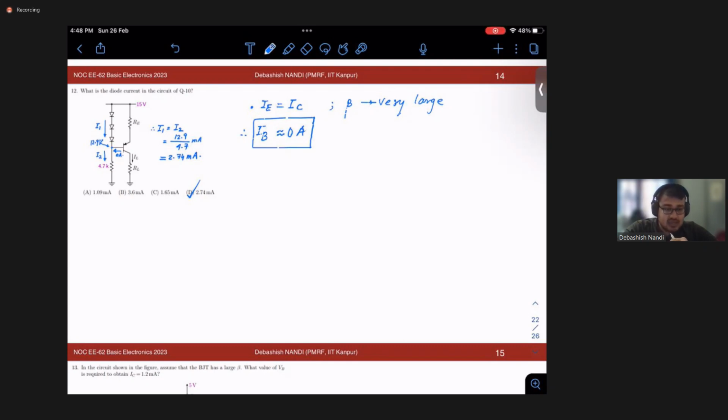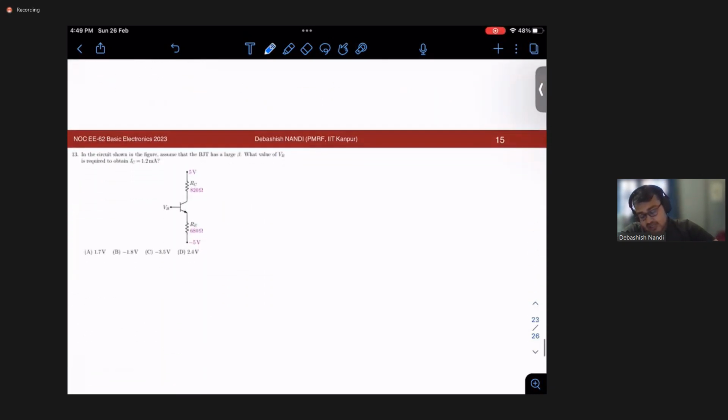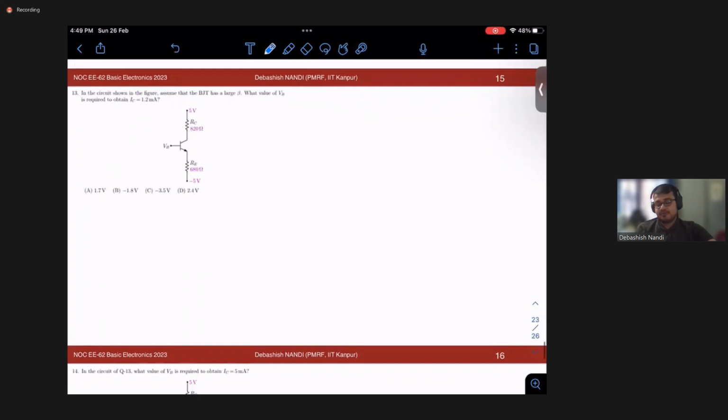So I think you will go through the lectures on various kinds of biasing, like voltage divider bias and other kinds. This is basically the fixed bias we are discussing so far. For various kinds of biasing, we will consider the Q point position, the quiescent point. Okay, we will go through the lectures and then we will discuss some problems on that. So let's move on to the next thing.